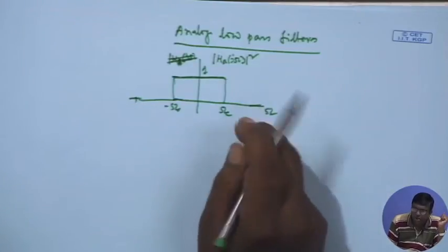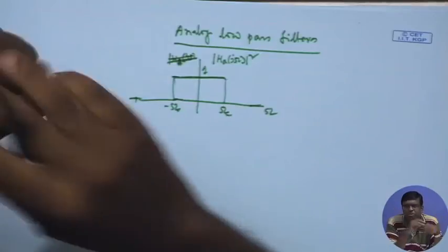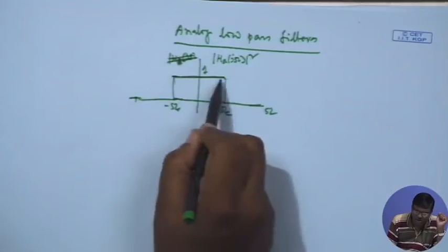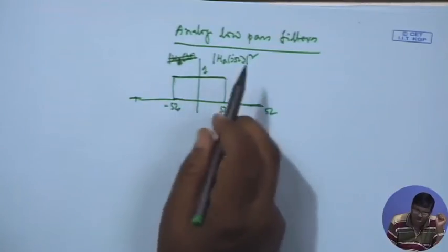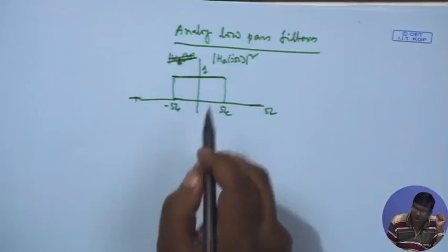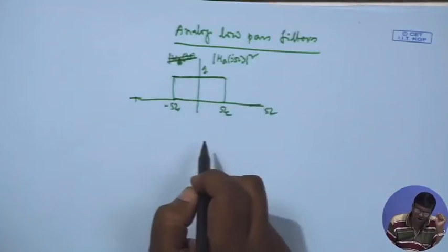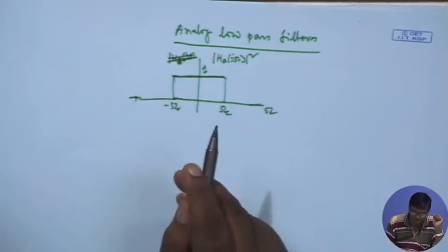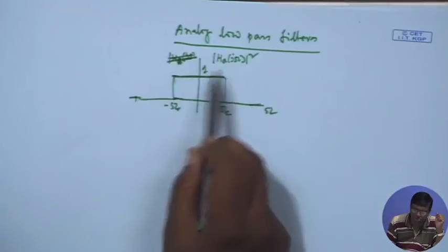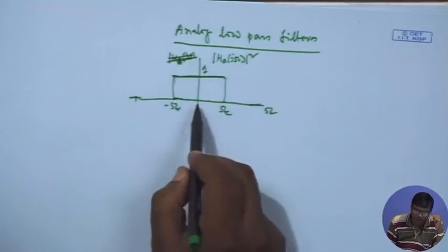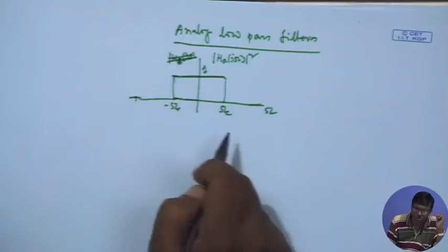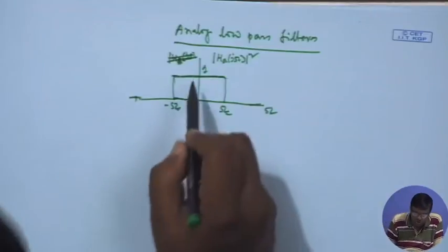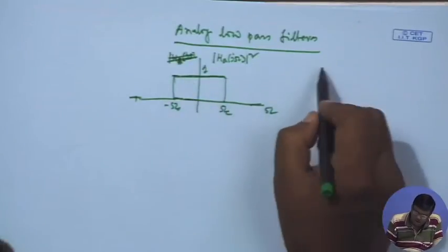Okay. Normally, the transfer function is given both by magnitude and phase. If it is ideal, the magnitude should be flat within the desired pass band of the filter, and the phase response should be linear in omega. But you cannot design to satisfy both. So what we do, we concentrate on satisfying the magnitude response as much as possible, and then we hope that the phase within this band is somewhat close to being linear, not very widely off linear. So, we will concentrate on this.